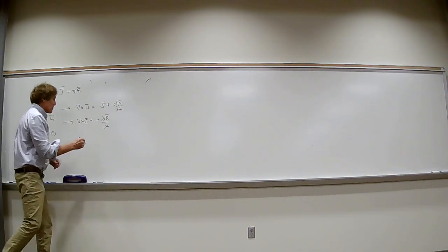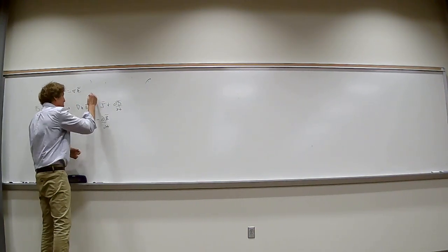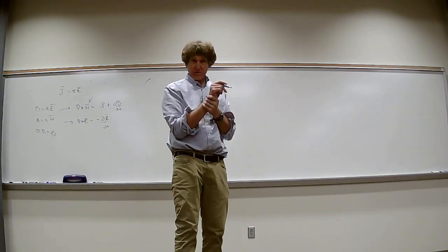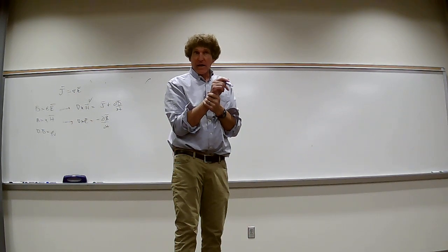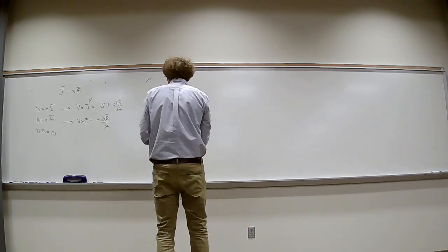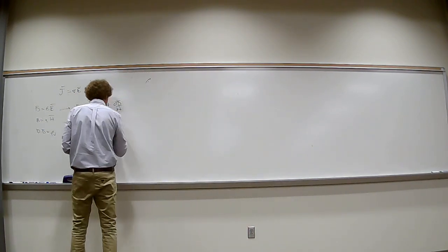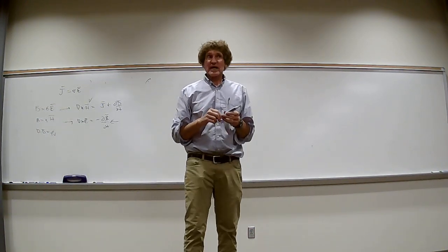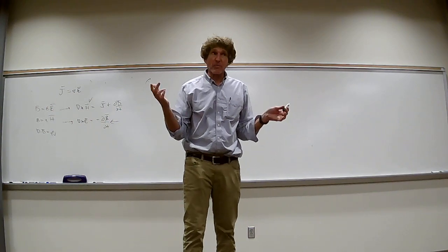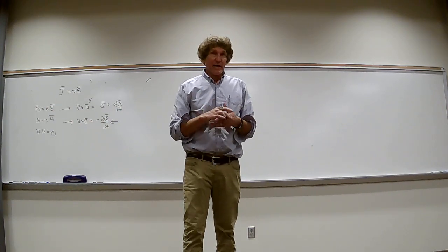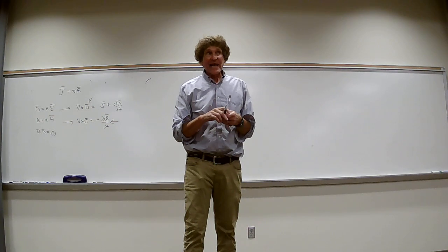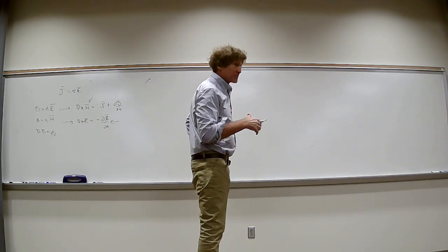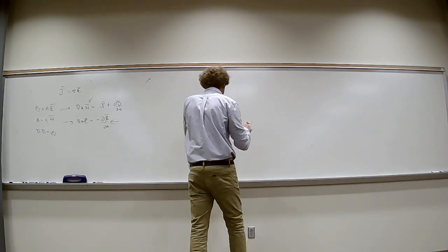Okay, now, when we have these 2 things, we did this one for actually charge decay. We took a divergence to get the charge decay, right? Now what we're going to do is work on the second one right here, Faraday's law of induction. And we're going to see how that actually allows us to calculate transformer action. You know how a transformer works, basically, right? You have to have AC, or has to have a time variation of voltage to get any kind of transformer action that's effective.